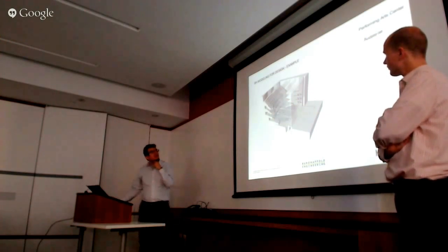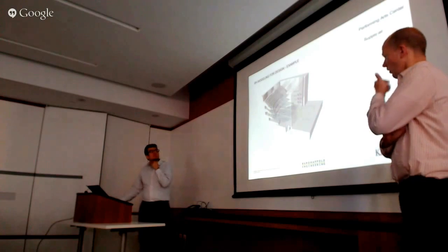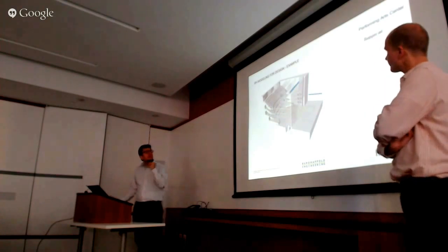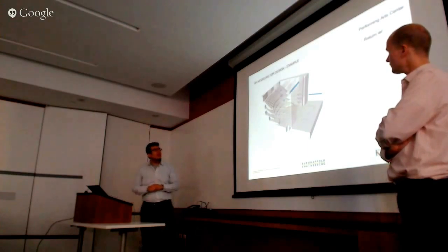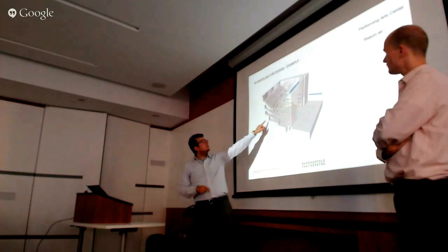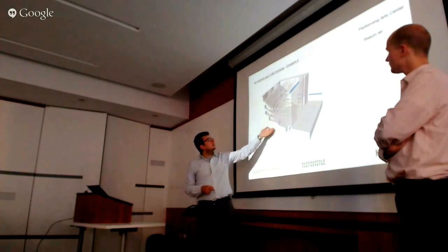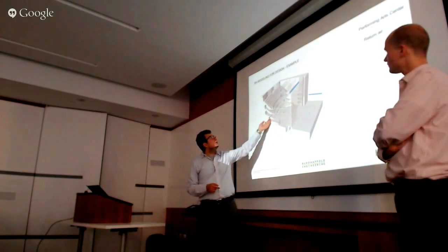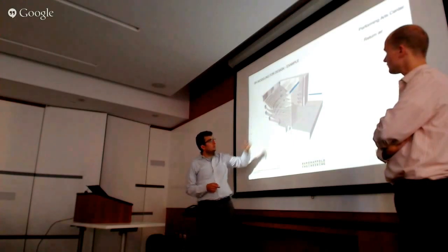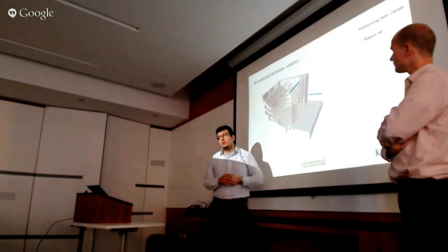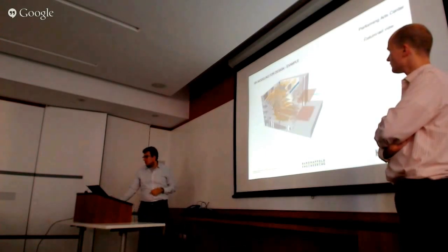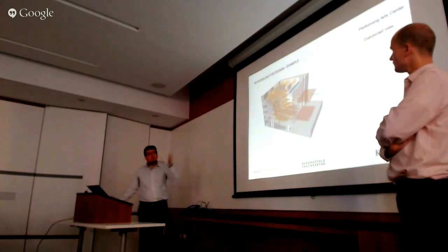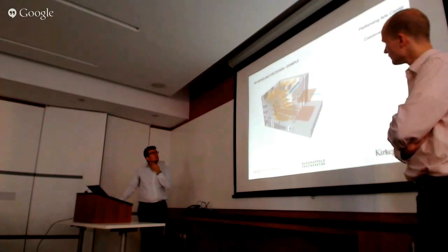And supply air, this was obviously for cooling, and return air. This was a main design driver because in the earlier iterations, we had not included the return air behind the first level. We had only relied on the upper three and the top one above the stage, hoping it would do the job, but it wasn't the case. I'm going to get to that. And overall, it looks like this when you overlay everything.